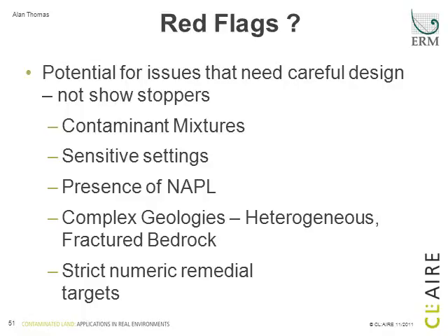This could include things like contaminant mixtures, whether you're in a very sensitive setting, the presence of NAPL, be it L-NAPL or D-NAPL, as has been mentioned, when you're working in complex geologies where it's very heterogeneous or where you've got fractured bedrock, and also where you work to very strict numerical remedial targets.